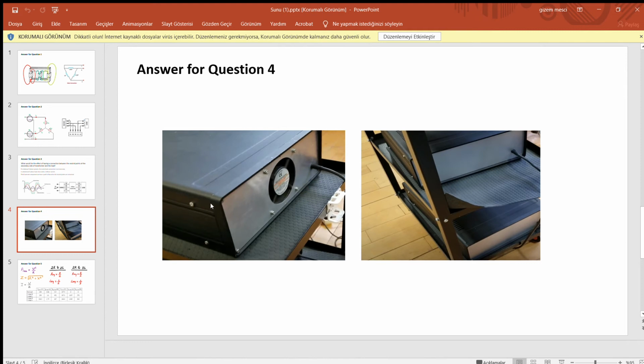By function, resistive load elements generate large amounts of heat. This heat must be quickly dissipated from a load bank to prevent overheating. Consequently, resistive load banks use forced air cooling, which is provided by a dedicated power circuit and one or more blowers. And here there is a fan on the resistive load bank.